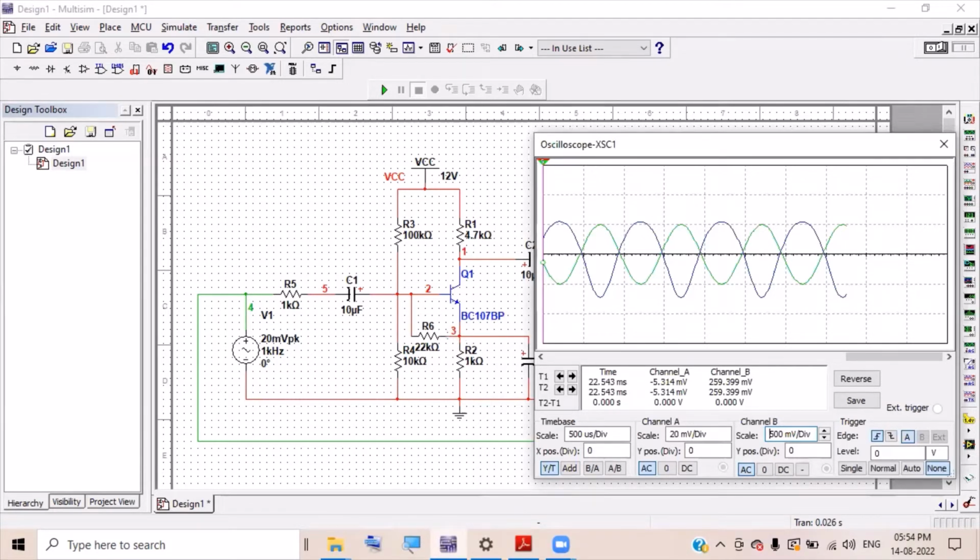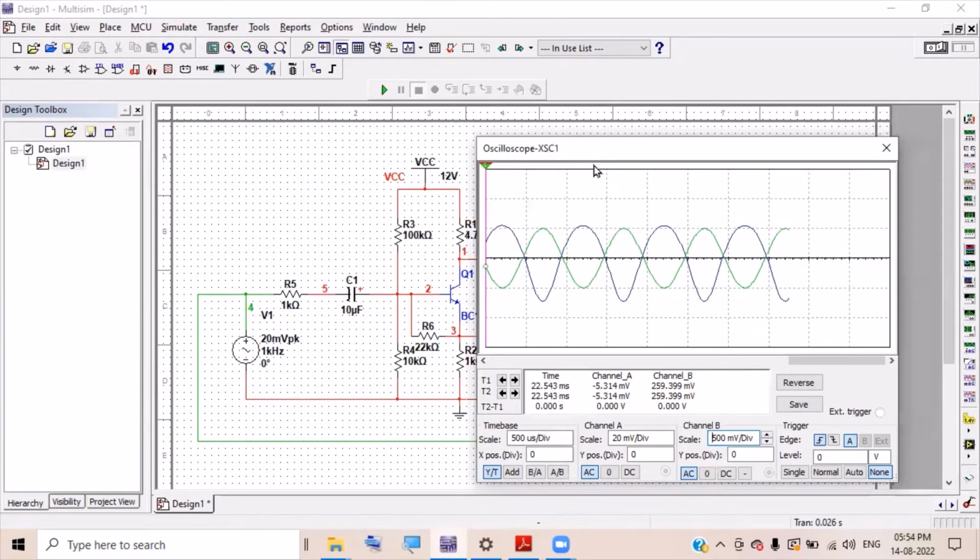We have earlier seen that 22 kilo ohm is suitable. So we have connected 22 kilo ohm here. Now what we will do is let us do the frequency response. Theoretically the gain has reduced because of this feedback, but the bandwidth will increase. So let us go ahead and check that.